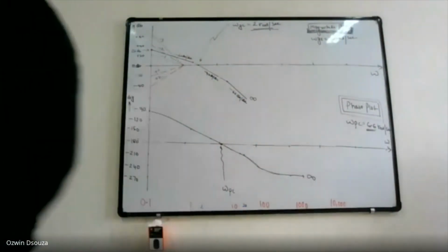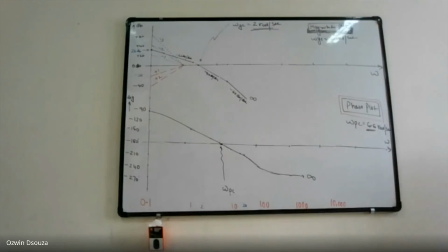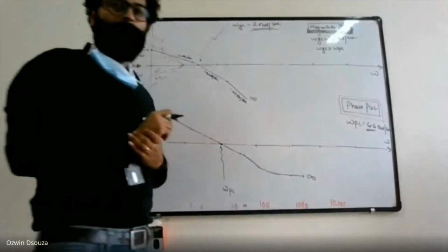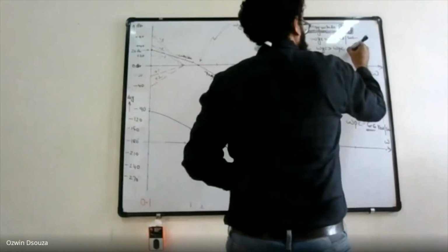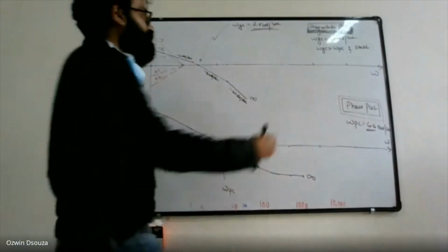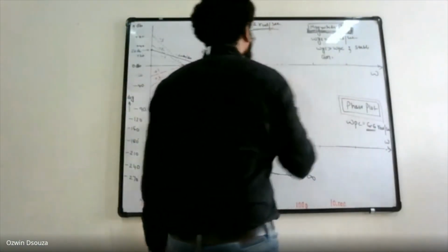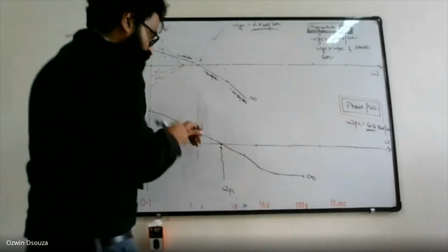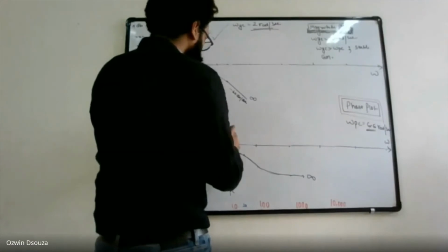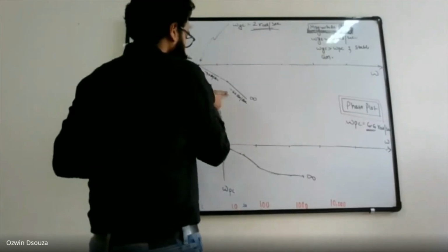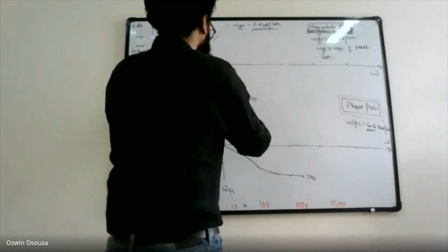Stability you can tell by looking into omega GC and omega PC. As omega GC is less than omega PC, the system is stable. And you can find out the gain margin. Okay. So how will you find gain margin? To find gain margin, from omega PC you have to draw a straight line vertically upwards such that it cuts your magnitude plot.